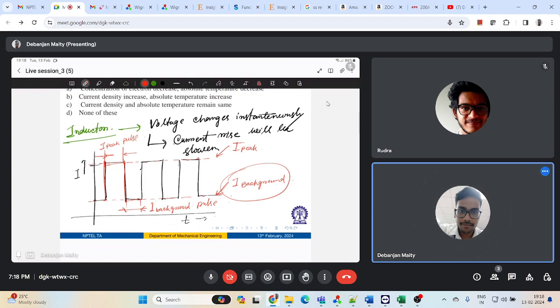The same supply unit can be made to work as a constant voltage source if you are doing gas metal arc welding, simply by changing the command signal, and it can be made to give constant current output if you are doing gas tungsten arc welding. So depending on your application, you can change your power supply unit to either CC or CV from that transistor power supply unit.